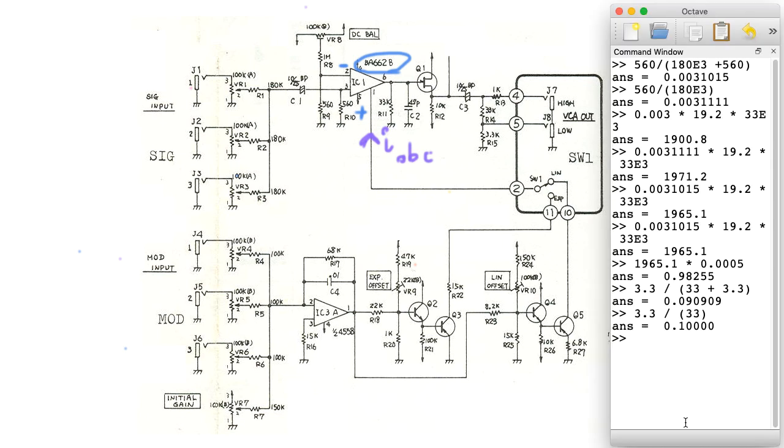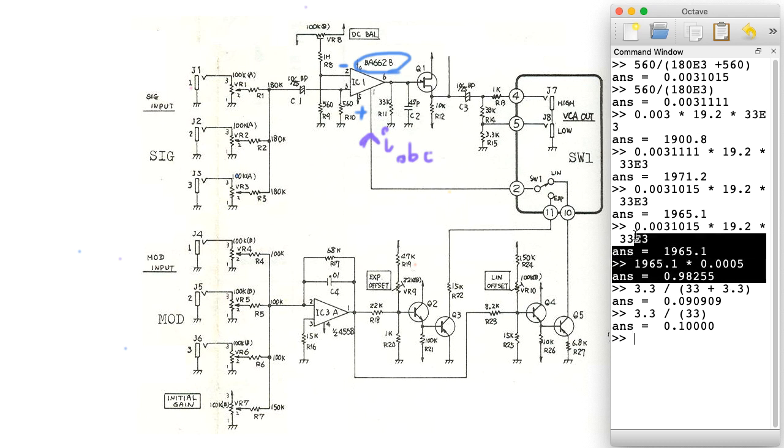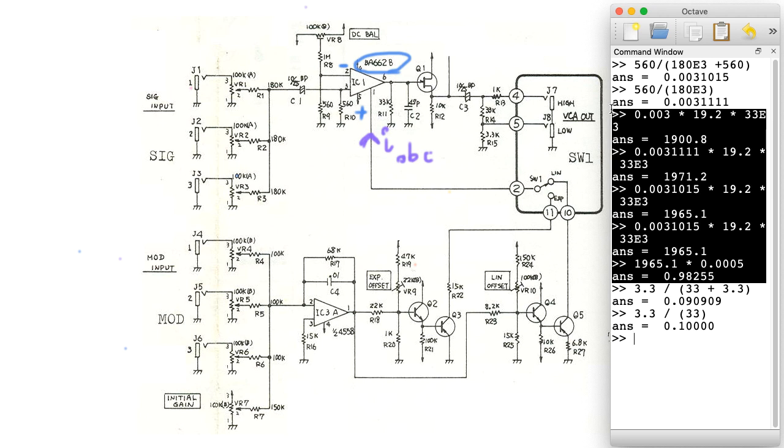So this is going to form a one-pole filter, but instead of a voltage in, voltage out filter, this is an impedance, so we can think about it as turning a current into a voltage. And essentially we have the same analysis, except instead of a 33K resistance here, we have a more complicated impedance. At DC, all of the results that I've computed previously still hold. So we can basically pile the frequency-dependent effect on top of that.